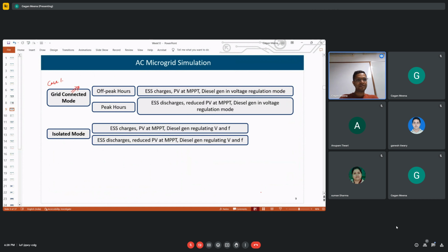Even before, when these converters were not present, there were other sources of harmonics. There are some loads which are non-linear, like arc furnaces. Even the transformer itself is a non-linear device. Do you remember any cause of non-linearity in transformers?